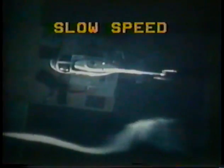This wind tunnel sequence shows the top view of the OH-58 main rotor disc vortex. The smoke is placed on the edge of the main rotor disc. Notice again that the edge of the vortex is well defined. The model is now positioned with a relative wind azimuth of 330 degrees. An actual aircraft at this point would have a tendency to yaw left into the relative wind. To maintain a constant heading in this position, a pilot would be applying a slight amount of right pedal pressure.